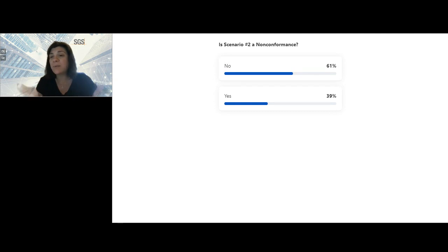If you know that you want to keep like a 2 meter distance or a 4 meter distance, whatever is needed to make sure that you can actually perform your activity, you can just rough measure it with a non-calibrated measuring tape. But if you want to be uniform within the company, consistent with all of your equipment, including a tape measure, then this is a decision you would take to say, yes, we are going to go ahead and calibrate it. But for all intents and purposes, under ISO 9001, there's no requirement. So you do not have to worry about calibrating a tape measure in this situation.